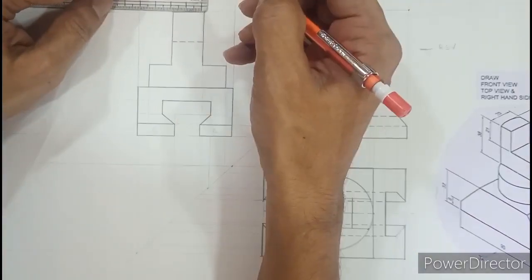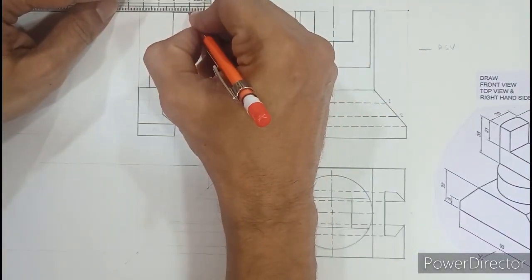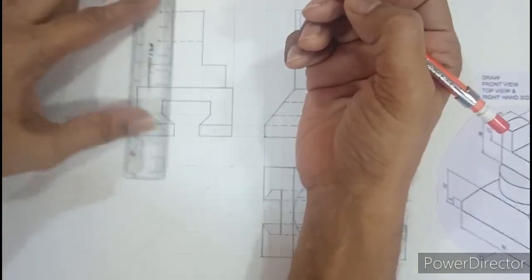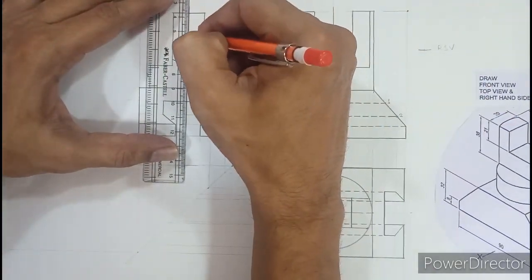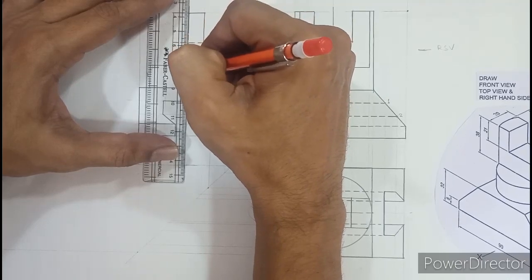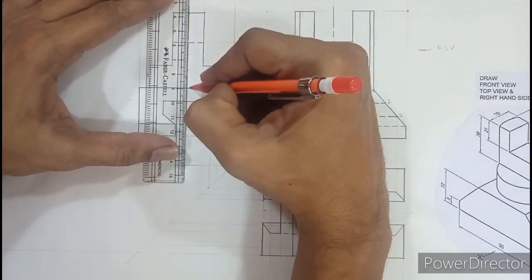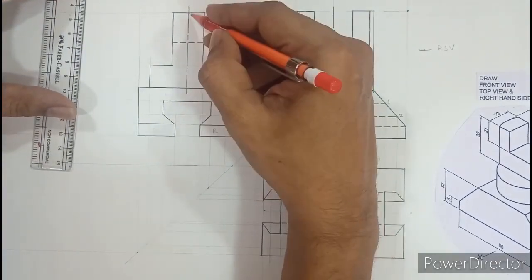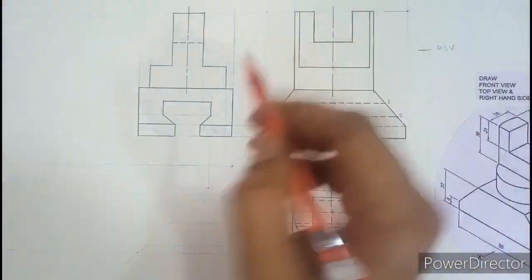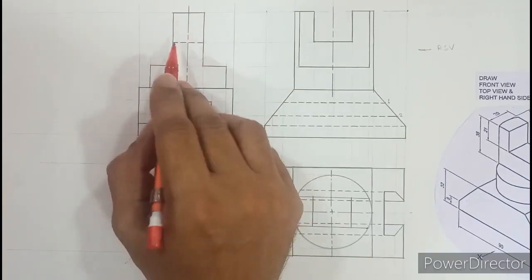So if you need, you can mark the midpoint of 20, say 10. Instead of projecting, you can do it like this, and then you can align the scale and draw big dash and small dash just in and around the cylinder. So see, the cylinder is only till here. You might extend slightly below, not throughout, and here slightly above. So this axis represents a circular surface.